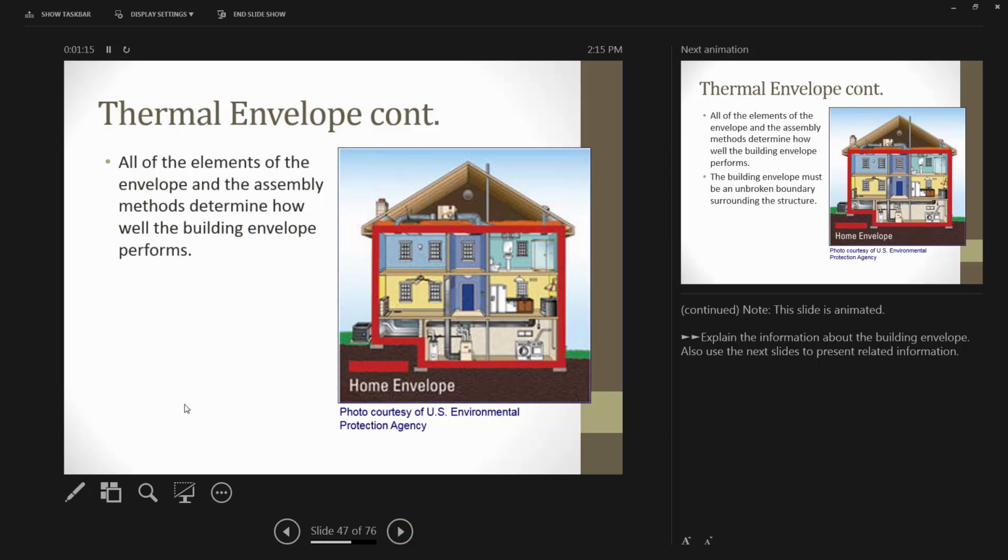So the thermal envelope isn't necessarily, as I said, it's a different sort of assembly. It's not one component. It's a series of components that combine to create that separation of the building from the inside, from the outside. And one of the most important things and the hardest things is getting that attachment and completeness of the thermal envelope. In order to control that air, in order to contain the heat, in order to contain the moisture drive, it's got to be a complete system.